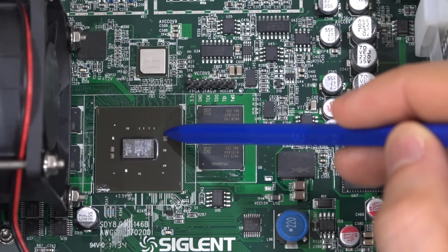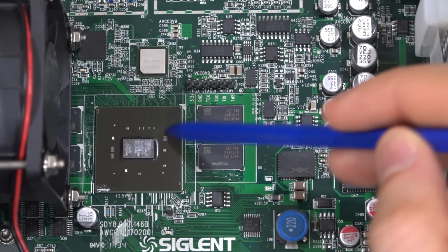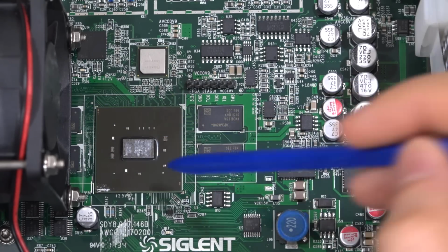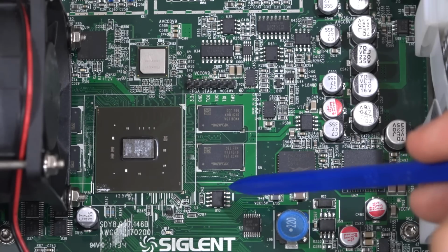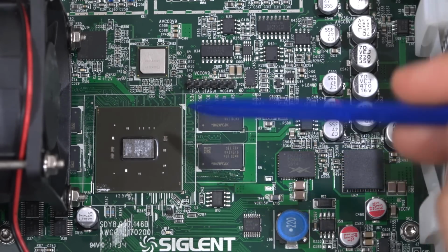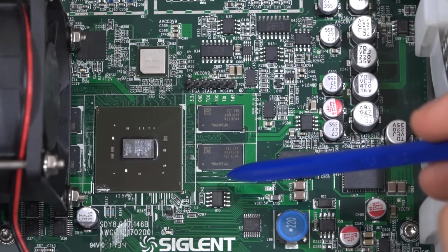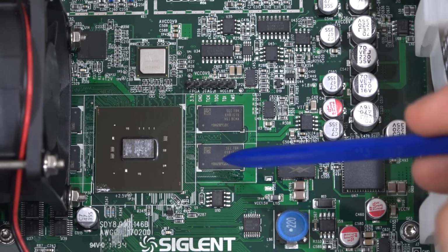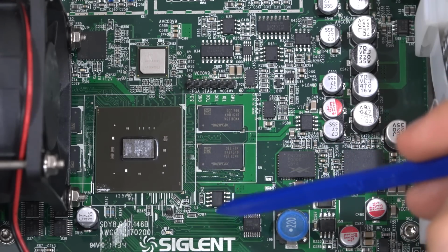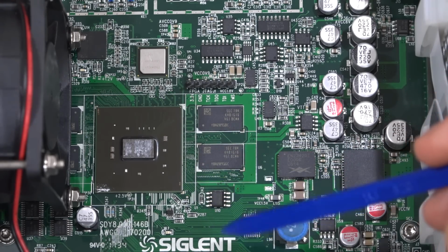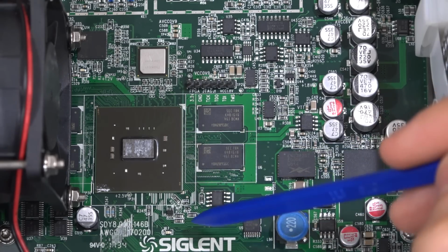That will be a huge waste of your FPGA resources. So therefore there is memory, as you can see, on each side, and these are also high-speed interfaces because you're grabbing data directly from the memory and then dumping it out to the DAC. Now these interfaces are all quite fast, and that's why you can see the length matching of the differential lanes that go between everything, but they also have to be fairly well isolated. So the layout is reasonably nice, and I like the way it looks, everything nicely put together.